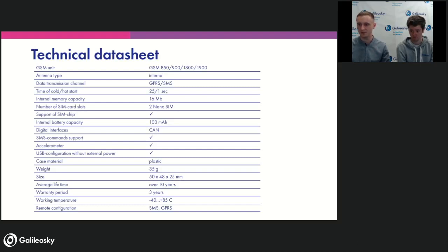For example, from Albertson Ape: what is the IP rating of the unit? Thank you for the question. Well, there is no IP rating for the OBD device, and there is one reason for that: it doesn't require one. The OBD port is placed in the cabin of the vehicle, which is obviously waterproof, and there is simply no case when it will be flooded or filled with dust. It mainly has electronic components covered by its plastic body. That's it, it doesn't require anything else.